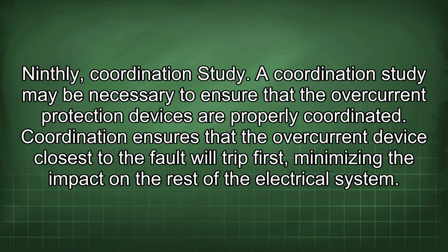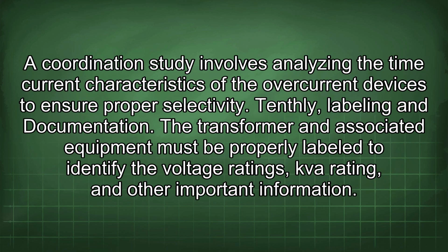Ninthly, coordination study. A coordination study may be necessary to ensure that the overcurrent protection devices are properly coordinated. Coordination ensures that the overcurrent device closest to the fault will trip first, minimizing the impact on the rest of the electrical system. A coordination study involves analyzing the time current characteristics of the overcurrent devices to ensure proper selectivity.